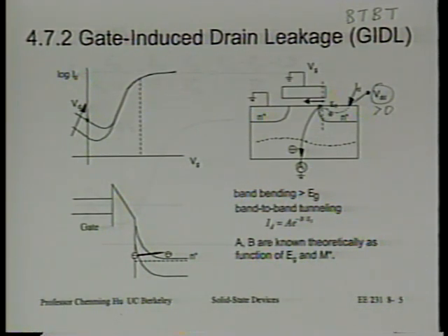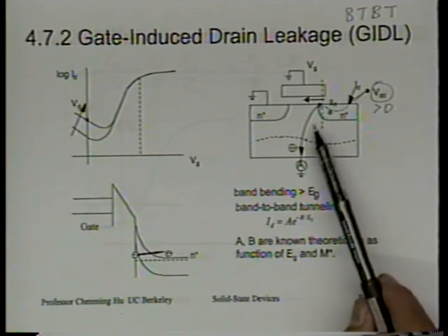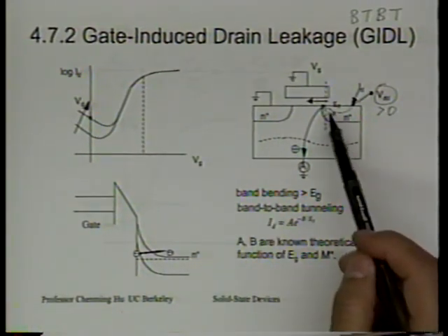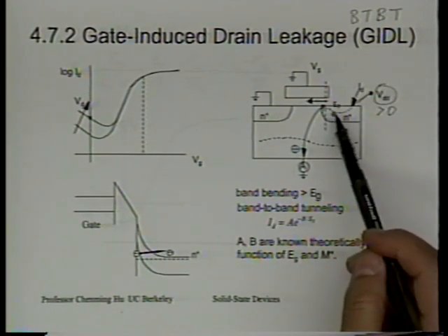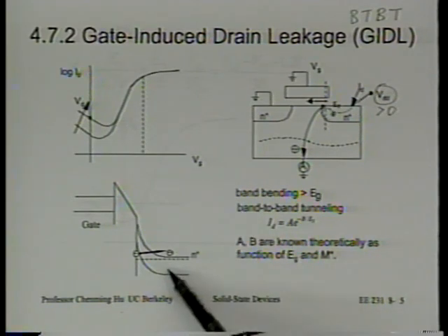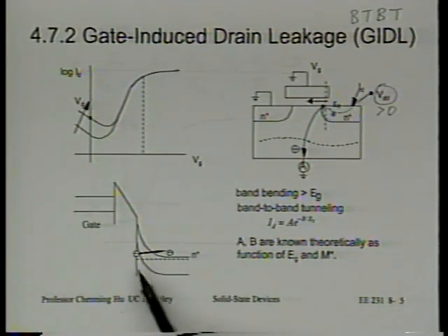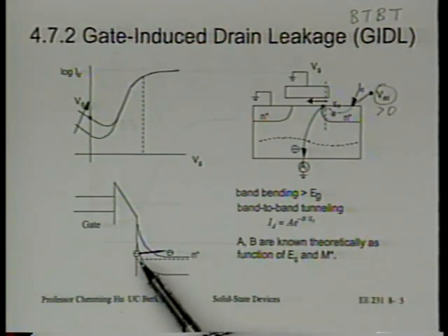Why is that? Right, because there's a so-called body bias, right? This is the body to source bias. Don't ask which is source and which is body, it's confusing the name. But the fact is, anytime you have a PN junction nearby with reverse bias, you know that the inversion will not happen at 2ΦB anymore. It's going to happen at 2ΦB plus VDD, okay? And by the way, before we even reach that kind of band bending, something else happens, namely this happens. So we'll not even reach 2ΦB plus VDD.